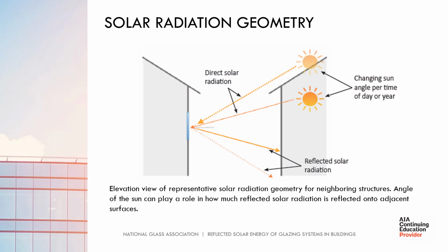The peak solar irradiance in the U.S. for a surface perpendicular to the sun occurs when the sun is highest in the sky. As the angle between the sun and the receiving surface increases, the effective solar exposure is reduced. Normally, for a high summer sun, low solar irradiance occurs on a vertical surface at midday, and high solar irradiance occurs on a vertical surface shortly after sunrise for an east-facing location and just before sunset for a west-facing location. For a low winter sun, high solar irradiance occurs on a vertical surface usually at midday for a south-facing location.